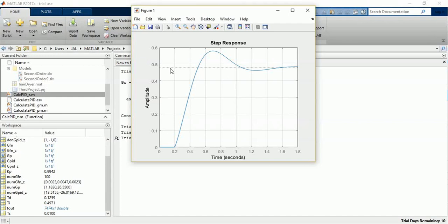There is a steady state error, and this is because there is no integrator in the direct path of the loop, and therefore we cannot guarantee a 0 error for a step reference. But the system is very robust, stable in that respect, on the response, on the overshoot, and we should be fine designing a PID controller for this one. It shouldn't be that difficult. So the next step now will be to see how can we implement that PID controller.